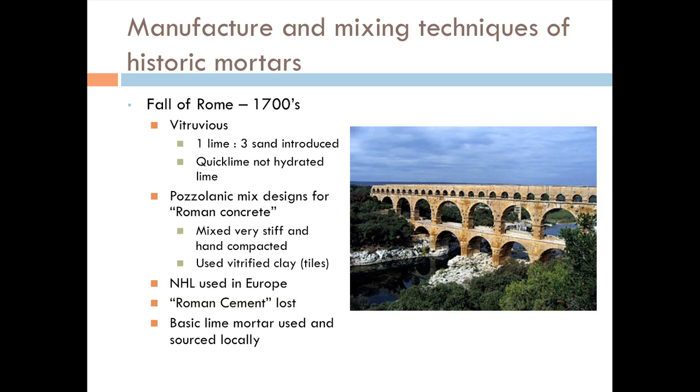Like I said, it was quicklime, not hydrated lime. There is a difference, even though chemically they are the same. One you can touch with your hand and add to water; the hydrated lime is not going to do anything. It's just going to turn into a milky putty type thing, kind of like cream cheese if you add the right amount. Quicklime is very volatile, and if it gets in your eyes, it can blind you, it can burn you. Very costly.